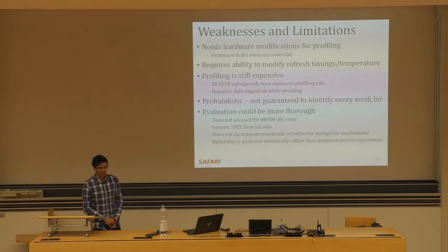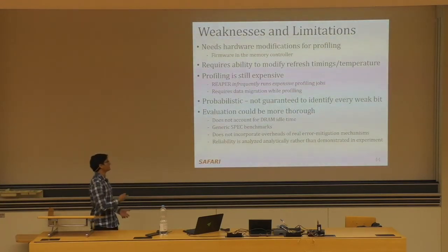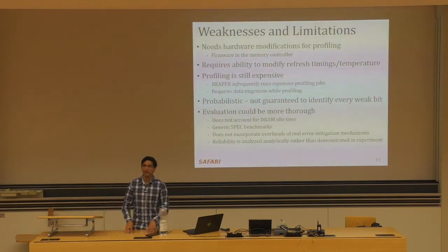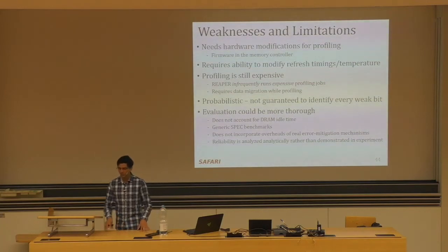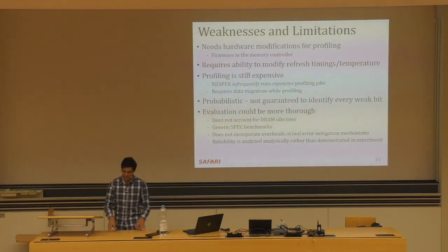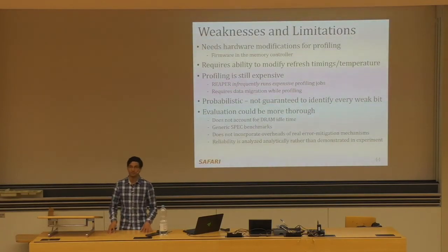And finally, as always, we can complain about the evaluation, right? So I think the evaluation here has several limitations. The first is that it does not account for DRAM idle time. And this is important because the characteristics of how the DRAM error patterns will look during idle will actually be quite different from during normal operation. Right? Because during normal operation, you're accessing the device, changing the data patterns, introducing a lot of circuit level noise to the device, which will cause the retention times to change much more dramatically than if the device is just sitting there idle.